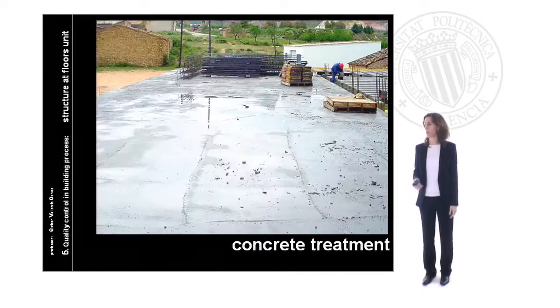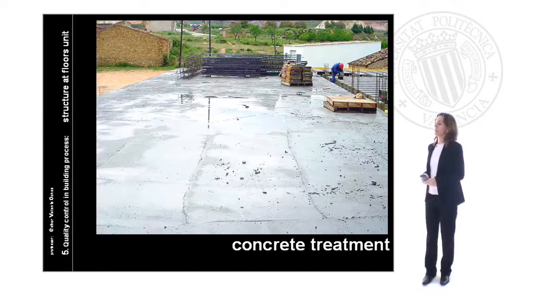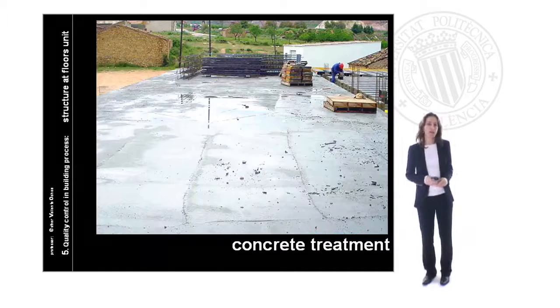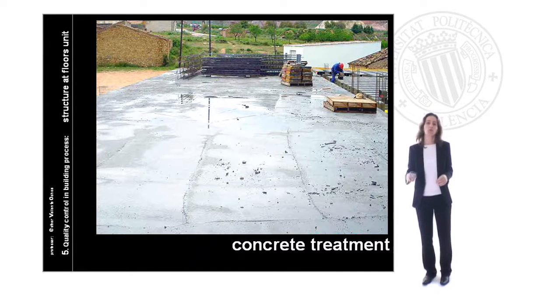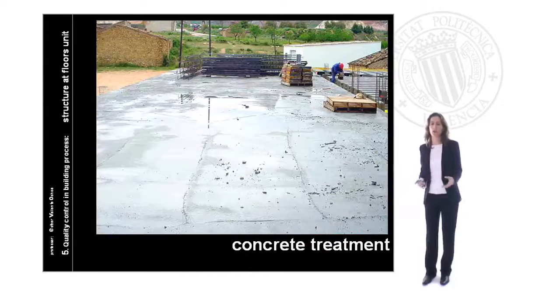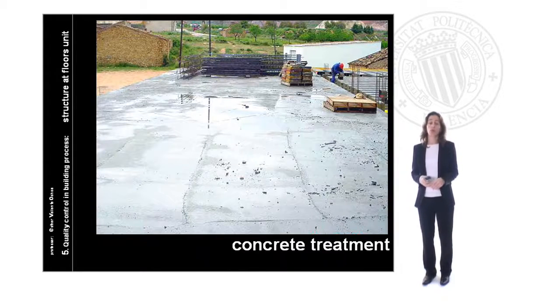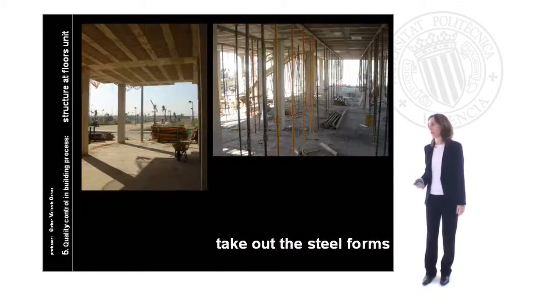The concrete treatment is an easy operation we can do, and we will guarantee we will have no little cracks in our surface. It's an easy thing and we have to do it because if not, the concrete will lose the quantity of water it has since the beginning.